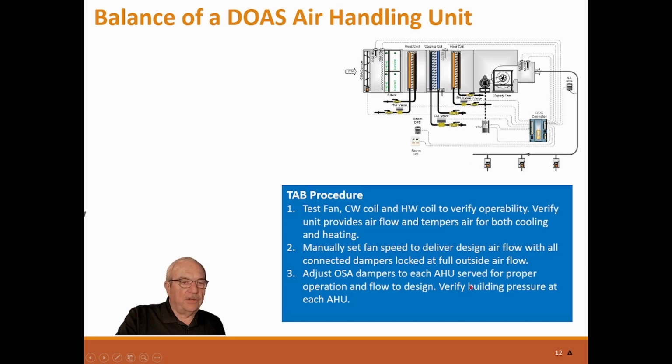Adjust the outside air at each air handler served for proper operation and flow to design. And verify building pressure. So we want to make sure these are balanced to design, and we have set this unit so that the building pressure is correct with these all at maximum at their design position.